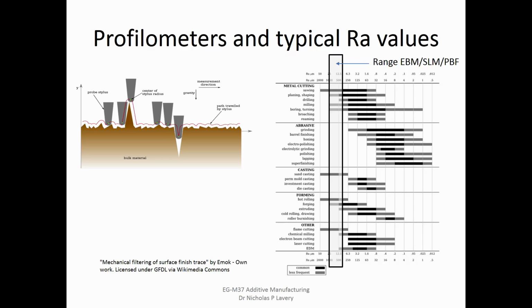So your grinding would be your first one, and then for polishing you'll start to bring in finer and finer sandpapers, and then finally you have a diamond mix or something which will polish up the surface. I'm not quite sure if you're referring to this kind of abrasion process. Yeah, that would put it in that order as well. Grinding would be the higher surface roughness.